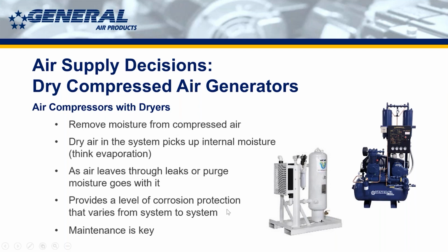And that's where I'd like to call out that dry air provides a level of corrosion protection that varies from system to system. Basically, the more leftover water, the less effective dry air is, and the better outcome you're probably going to have with a nitrogen generator. But in a properly pitched, properly drained system, where most of the water is getting out after the fill tests and whatnot, a dry air generator is a great way to go to limit or inhibit corrosion.